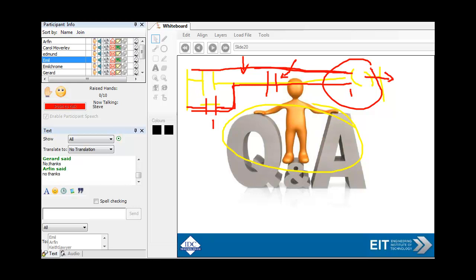Yeah, look, we will be going into more depth on PLC programming with some examples in the future sessions, but all we want to do now is just say to you, there's a whole heap of instructions, digital input, digital output instructions, power flow, which energizes a coil, and then once you've got the PLC programming understood, you then need to move on to the understanding of the complete system. In other words, the holistic view of the system.